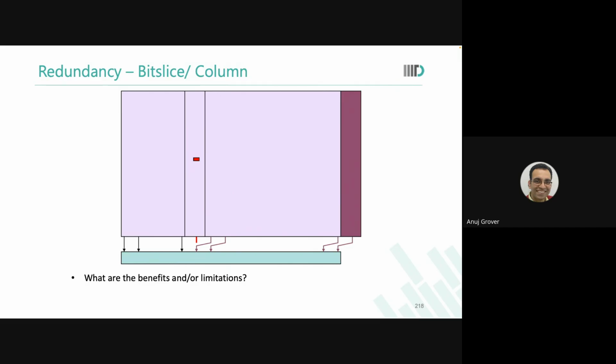Whenever you get design choices, you have to always compare them on at least P, P and A. Are you able to see this? This analysis you should always be able to do. This is extremely important. So there is nothing like column redundancy being better or worse. You could use bit size redundancy and the size of your comparator would immediately reduce, but somewhere else you will need to give up area.